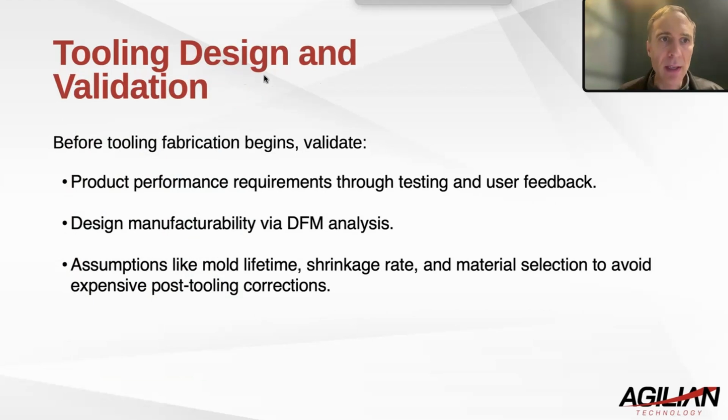Okay, the design and the validation of the tooling itself, of the molds, typically. All right, very important. Try to do testing, try to get user feedback as much as possible, usually based on 3D printed parts. More and more what we do is we actually do 3D printed molds to very quickly do plastic injection molding of these parts and then test them.